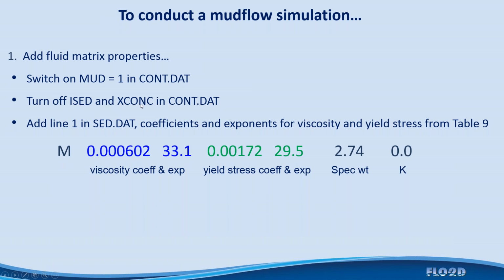If you're just doing a bridge design or something, you could do this because you want to make sure you account for the sediment. Otherwise, you're under-designing your bridge for the 100-year event, especially if the concentration can get up to 10 to 20% concentration by volume. At 20% concentration by volume, you're somewhere on the order of about 25% bulking factor, or 125% bulking factor. So that's important.